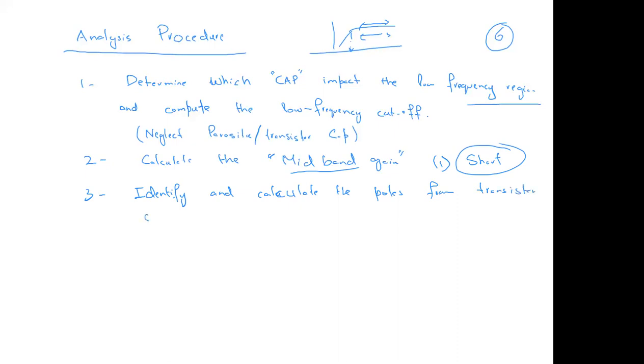The transistor caps, or any load capacitance, because of them we'll find the poles which are in the signal path. Again, for this configuration, we are going to ignore or short the first part. The capacitances we identified above for the low frequency, we will ignore them because they are not going to impact the high frequency. And now we are finding the high frequency basically.